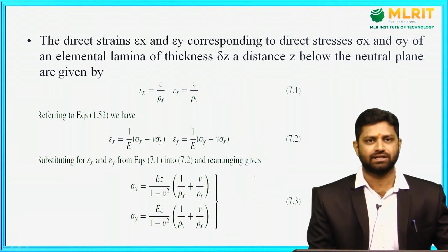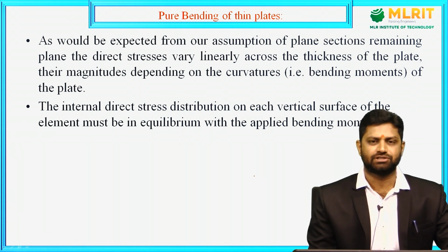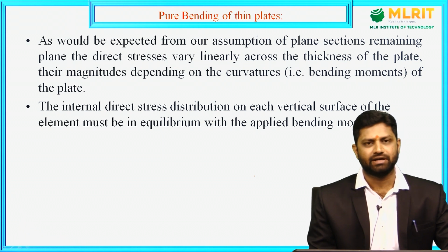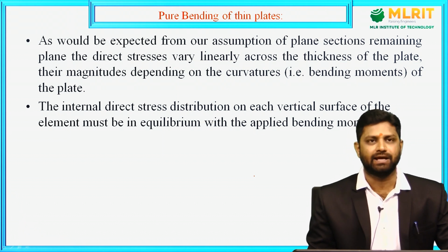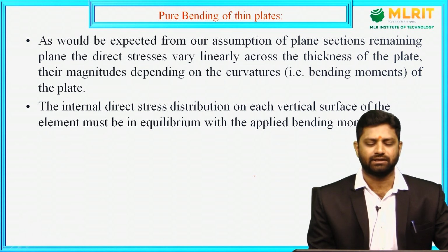Now let's extend this analysis. We have one assumption we've seen in the previous session also, in the thin plate assumptions, that plane sections remain plane even after bending. Whenever we consider this assumption, direct stresses vary linearly across the thickness of the plate, and therefore their magnitudes depend on the curvatures of the plate.